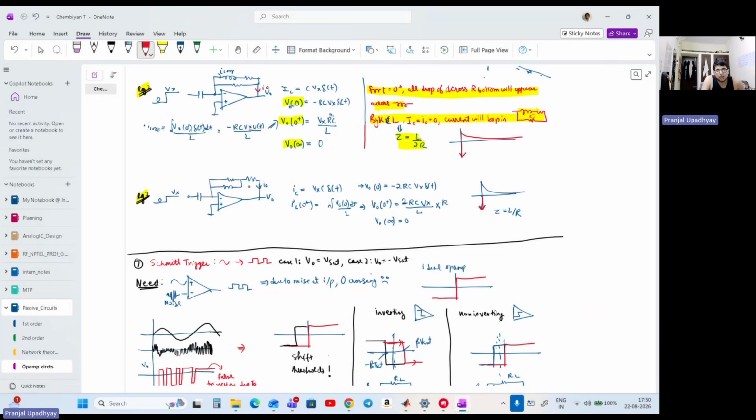After this impulse has transpired, all of this voltage that appeared between these two resistor terminals means there will also be some voltage across this resistor, and as a result there will be a voltage across this inductor also, right? And that will also be of impulse in nature. Because we can understand by voltage division that half of the voltage will appear across this resistor. These two resistances are equal, and thus there will be some sudden voltage appearing across the inductor. By virtue of this, we'll have a unit step current which will initially develop, which will be the initial value of current through this inductor.